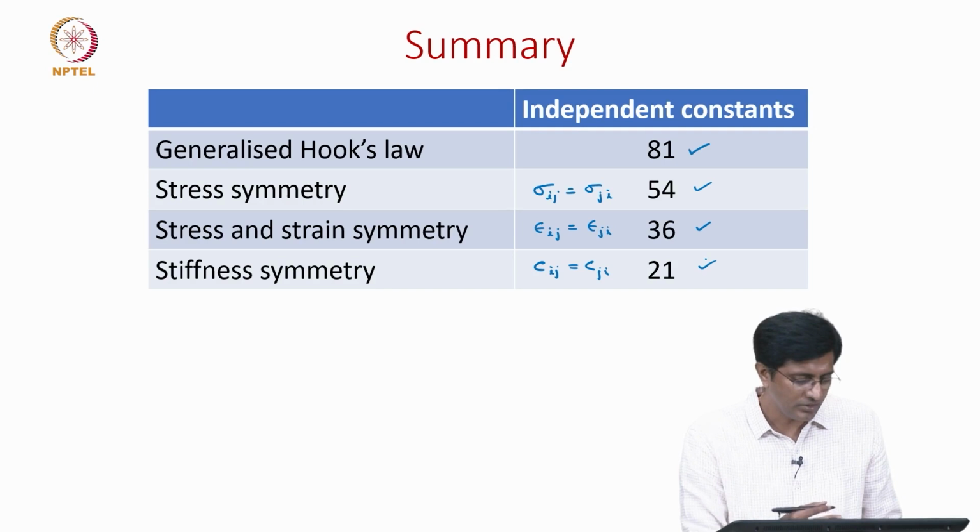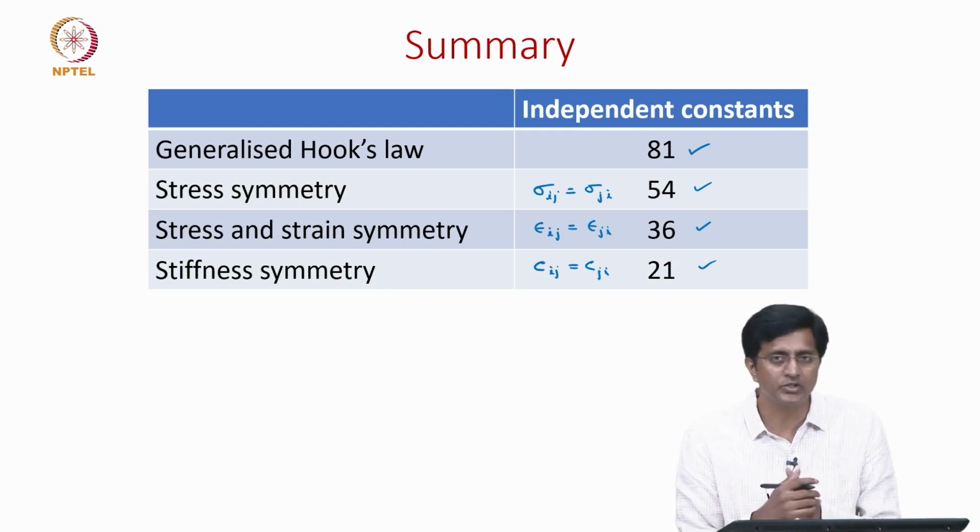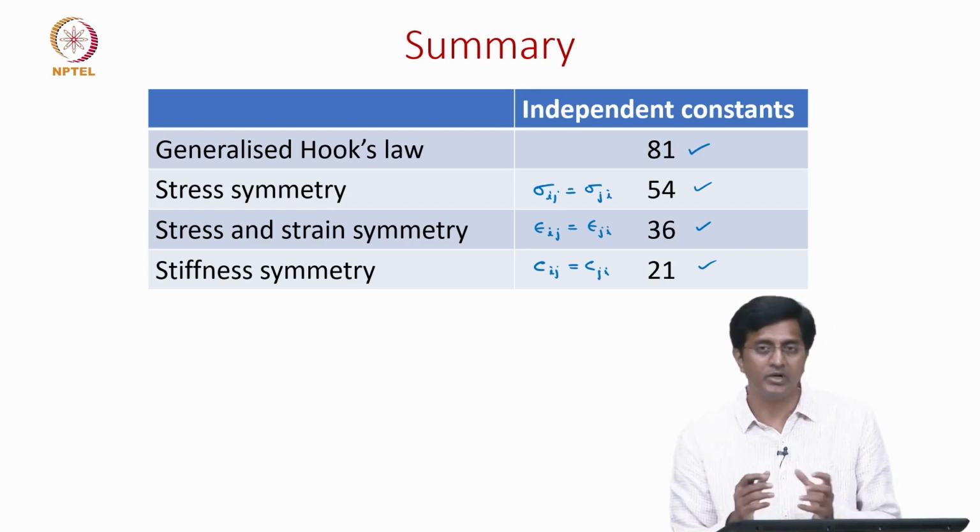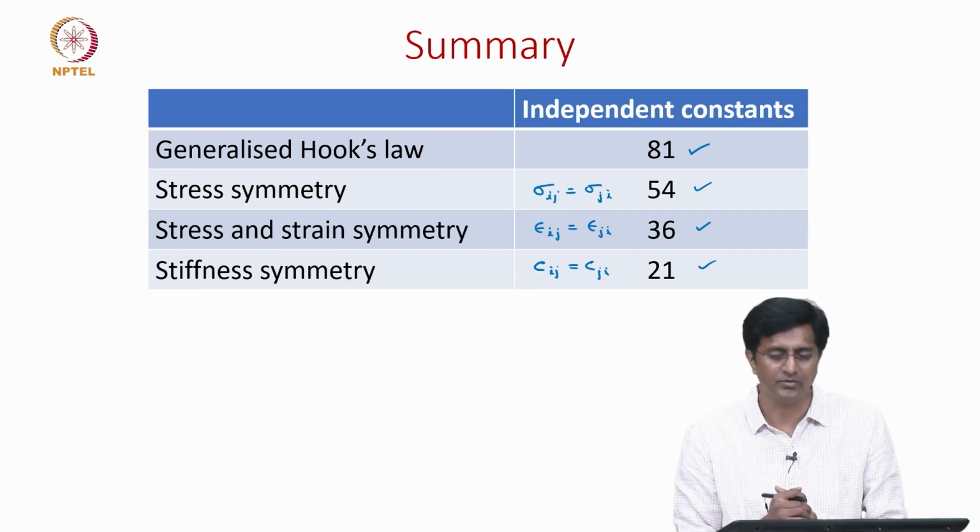Though here I write only the stiffness matrix, we have also shown that the compliance matrix is symmetric. And lastly, we tried to get a sense of this compliance matrix, looking at the significance of each of those terms and where the coupling occurs. So, with this we will conclude this video. In the next video, we will look at further simplifications.